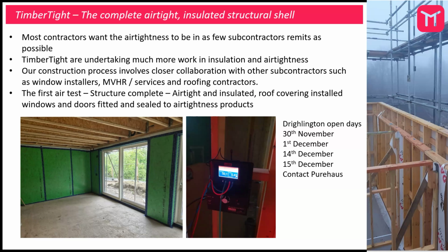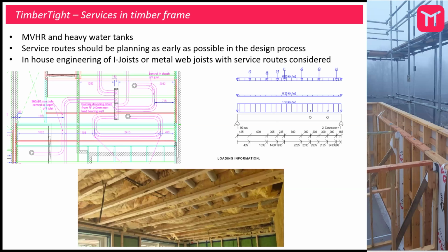So this is again from the Driglington site, and it shows where we finish, which is the first air test before any of the services go in. We test the building, we work with the window suppliers who install the windows, then we tape the windows, and we find that that's what contractors are requiring now, is that we provide the full airtight structural shell that's fully insulated.